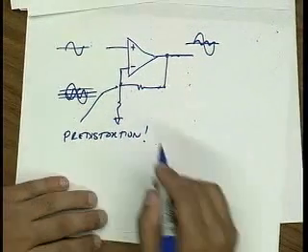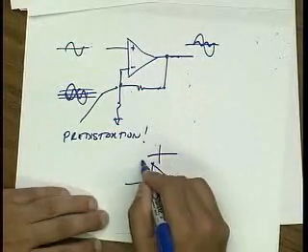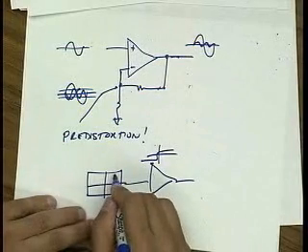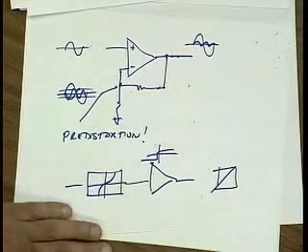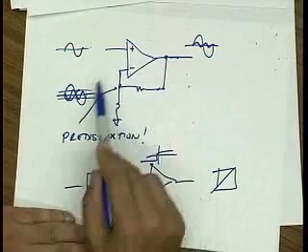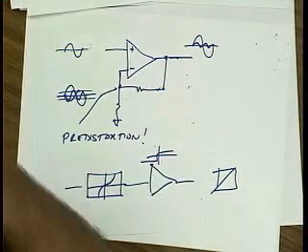It's as if you took your nonlinearity, let's say this is a compressive nonlinearity, and you pre-multiply it by an expansive nonlinearity, right? So that the overall transfer function is linear. Well, this expansive nonlinearity is being generated by the op-amp through the action of the feedback.